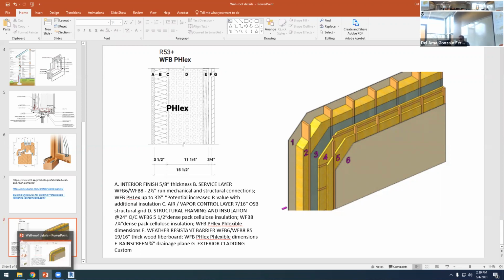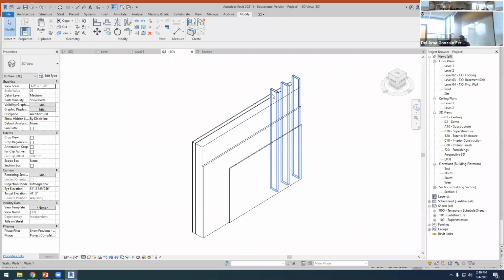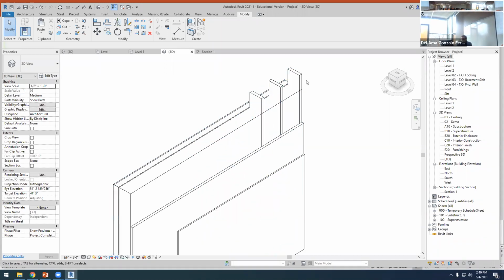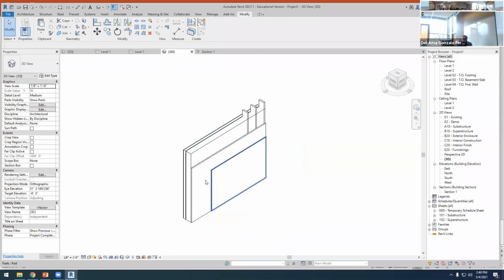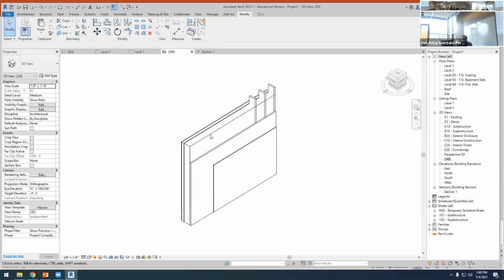So this is what you have to do today using the Benson wood detail, and then you have to add colors. I'm not going to do that, you know how to do it. And you have to use the same color code that you used for the roof. So if you have used the yellow color for the thermal insulation, you would need the same yellow color, the same color that you have used for the wood. But you can work with this, and we need a section, and we need a 3D view, and we need a list of materials that this wall is made of.